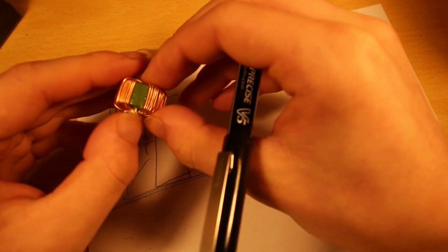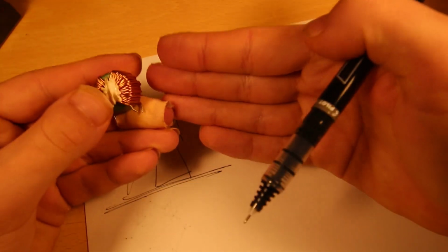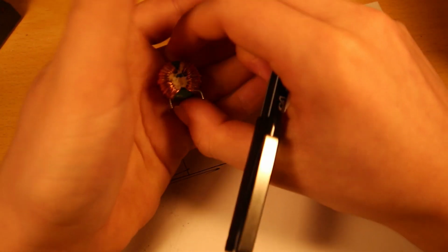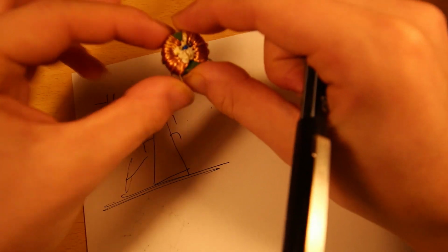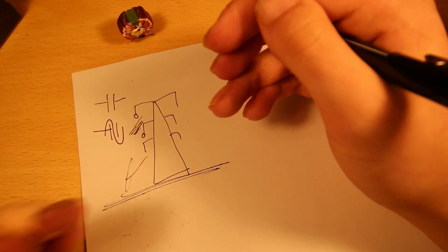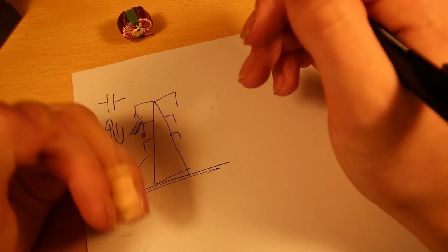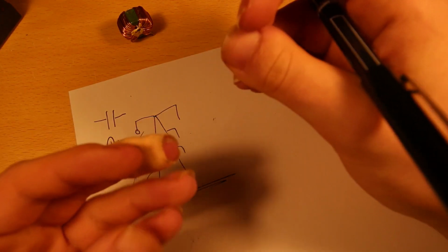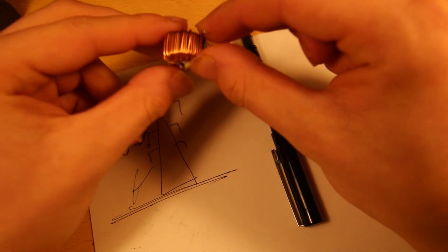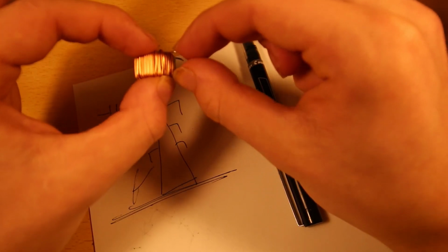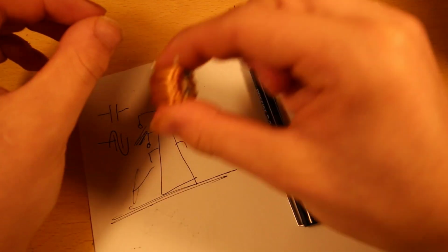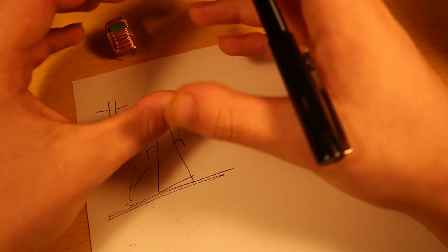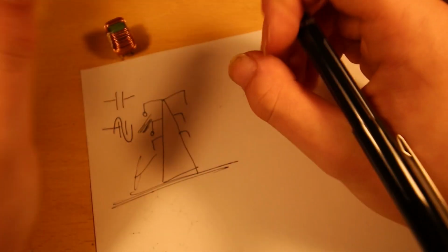Because AC is changing direction, inductors will oppose a change in current. The magnetic field I was talking about will build up in this coil, and it gets stored in the magnetic core of this inductor. And when you try to change that, so when the AC turns around to go back down or whatever, the inductor will fight that and create an opposing force, which is the inductive reactance. So the coils on this might only have a resistance of, say, 1 ohm, but the inductive reactance of this will be much, much higher than 1 ohm. So they will also leak current. The inductive losses are less bad.